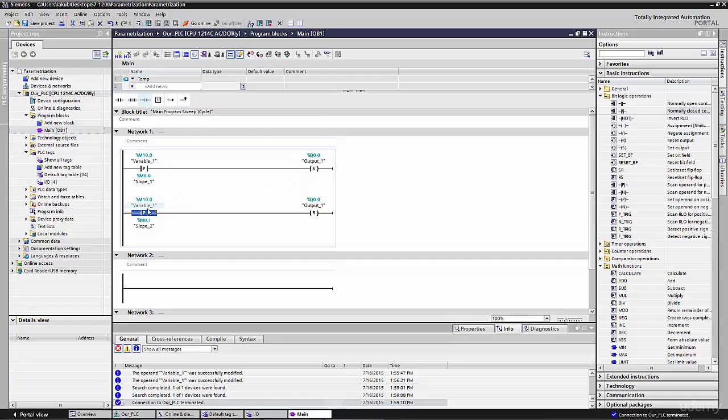But after a very short time, in one cycle, so it is shorter than 1 millisecond in our case, it will be reset in the next line. So the solution is that our output will always be reset. We will not see any change of the state. Of course, if our output was switched on before writing this program, it will be switched off on the rising edge.